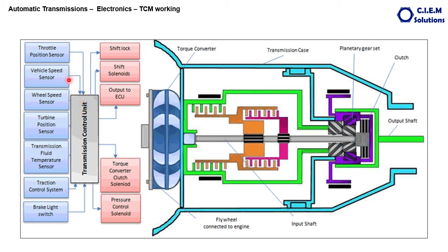In addition to these two sensors, various other sensors are also important for the precise functioning of gear shifting. Wheel speed sensor. Modern vehicles are fitted with a wheel speed sensor. The wheel speed sensors are installed near the rear wheel to give more precise outputs, because sometimes there will be drive slippage in the vehicles on account of various road conditions.